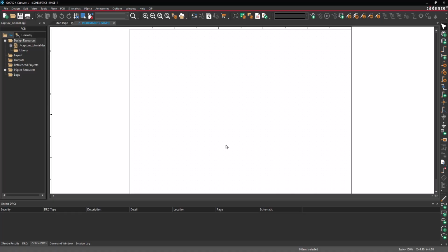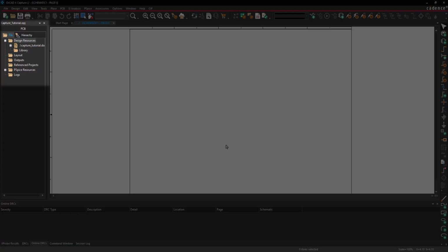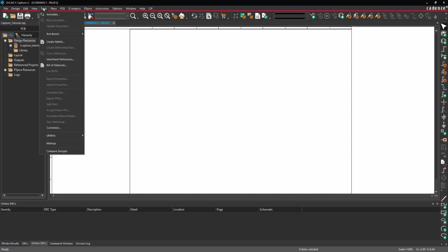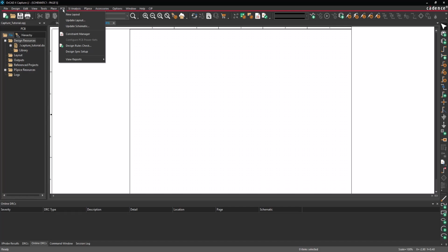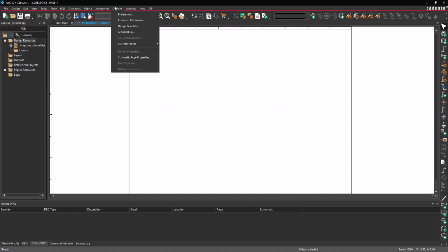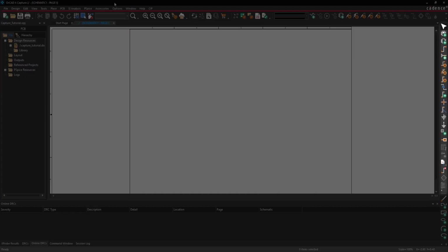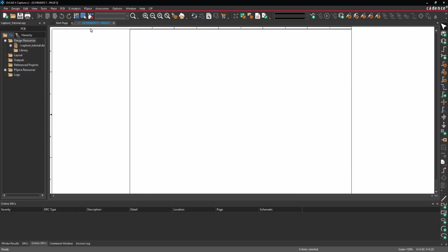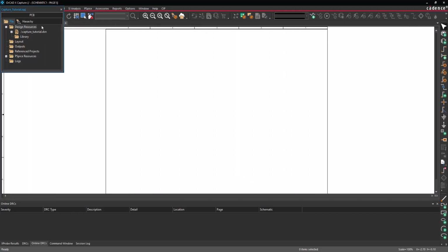The Capture workspace is fully customizable to improve efficiency. The design hierarchy is visible to the side of the schematic. Multiple projects can be opened and toggled between using tabs at the bottom of the Project Manager. The menu bar includes various options to customize and export the design, place objects, create a PCB layout file, customize the interface, and more. Toolbars include commonly used commands such as Save, Load, Zoom, or Find an Object, as well as common schematic commands such as Component and Wire Placement. Toolbars are fully customizable and can be moved throughout the workspace. Individual panels can be floating or docked depending on your preference.